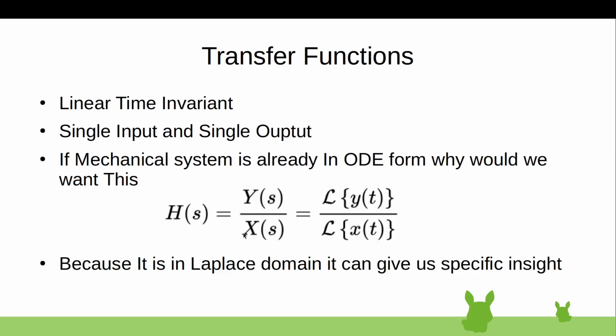And what would that be? So that would be F over m s squared. And if you look back to the top of the first thing that you wrote, what would be F over m? That's right, it's acceleration. What is 1 over s? Integration. What would 1 over s squared be? Double integration. So acceleration double integrated is what? That's right, it's position.